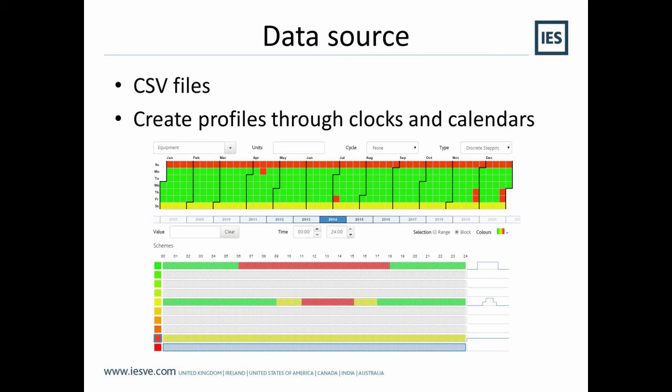At the bottom, you get to choose from maybe 10 different daily profiles. You can input your values to control the shape of each day. So that's like a 9 to 5 on off, maybe an 8 to 4 stepped profile, and this one's maybe 50% occupied continuous. What you then do is use the colour swatch for each of the profiles, and click on what pattern you want that to be.